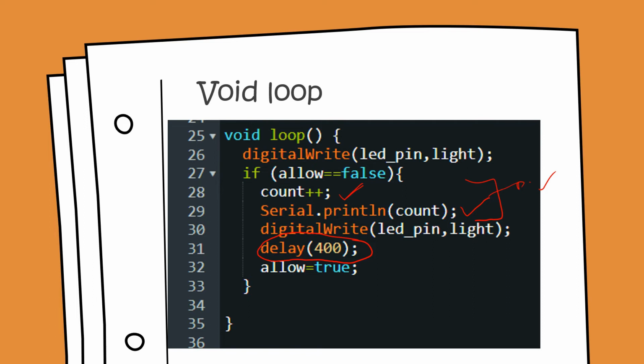It's important because when we use a mechanical switch, the transitions are not exactly clean. We go from high to low and then low to high, so this is what we expect. But what actually happens is that you go from high to low, and then there's a lot of chatter before it settles to low. Similarly, when you go to high, you have a lot of chatter like this, and then you settle down here. So this region is the region in which the switch is actually bouncing.